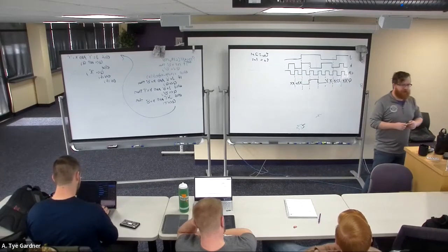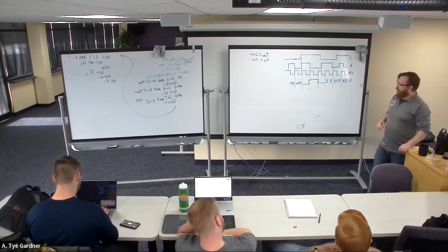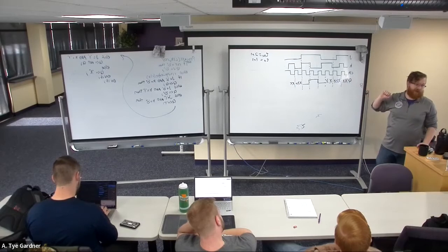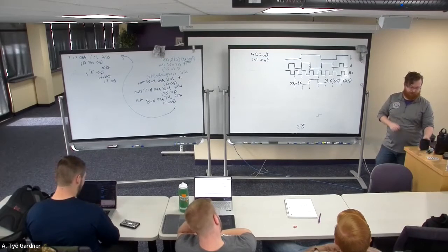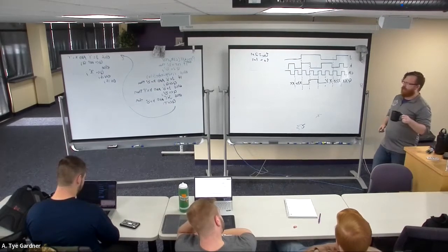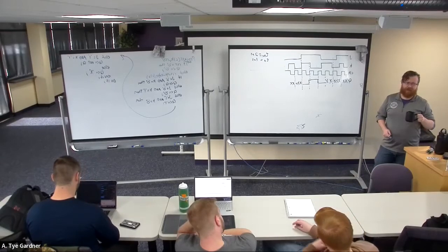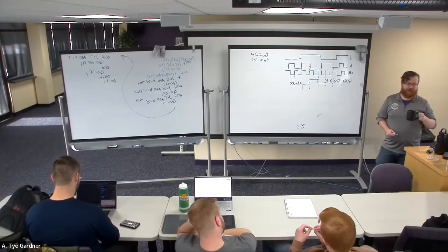We're not going to have any clue what it is. The downside of simulators is it will give you an answer, but then you're going to put it on the FPGA and it's not going to work. Worse, it's going to often work sporadically. Like it'll work 9 out of 10 times, and hunting down those intermittent errors is a nightmare.